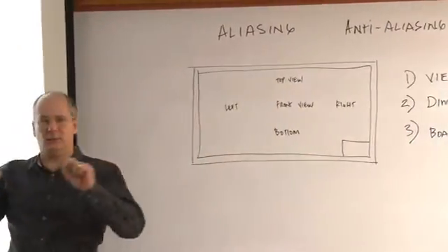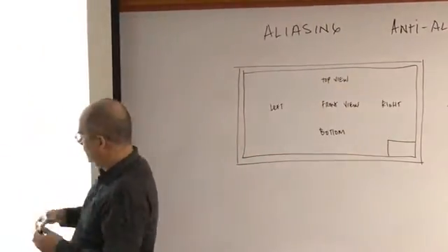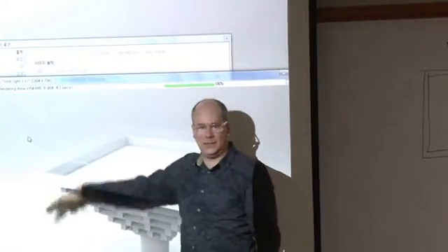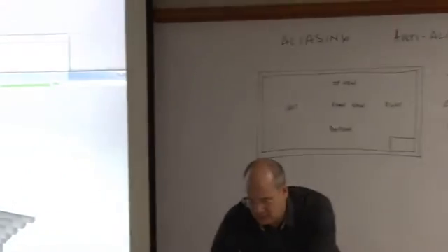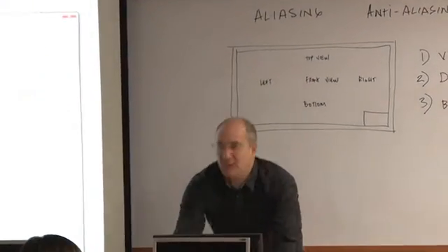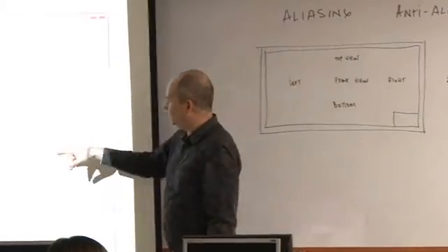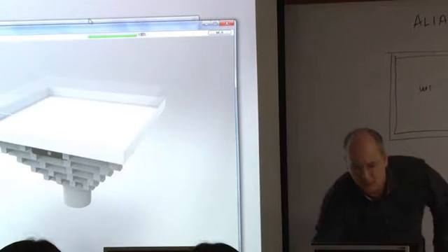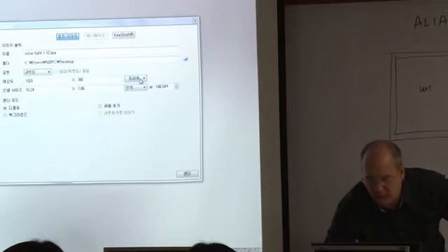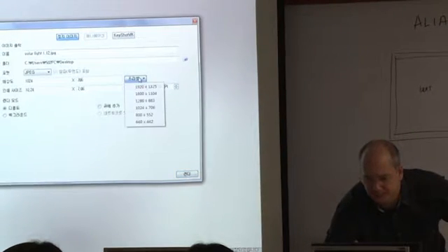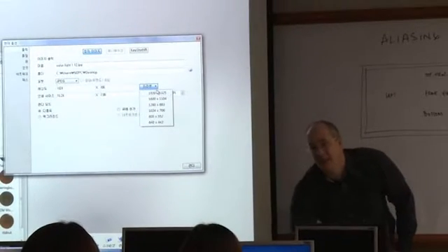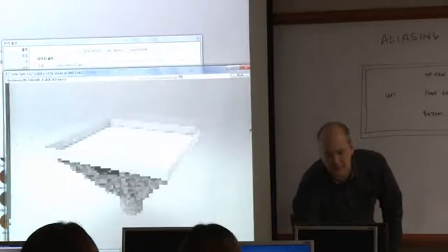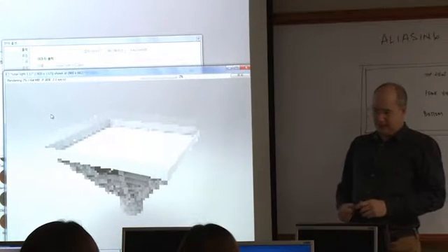Okay, so when you're trying to get really tight imagery, you have to be aware of your edges. You can see how that edge is pixelated like that, okay? So we want a really tight image of this. I want to apply some control to my resolution. So let's close this and go all the way to the highest resolution, 1920 by 1325, and then let's render it. This might take a little bit longer.